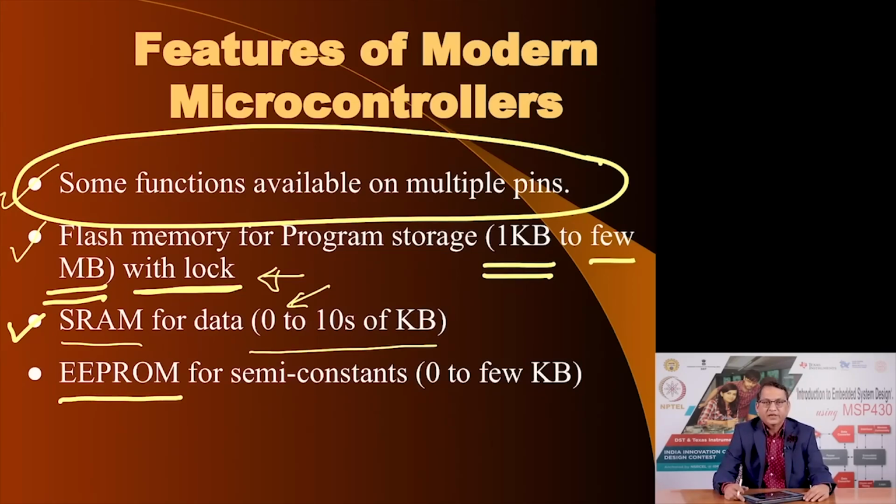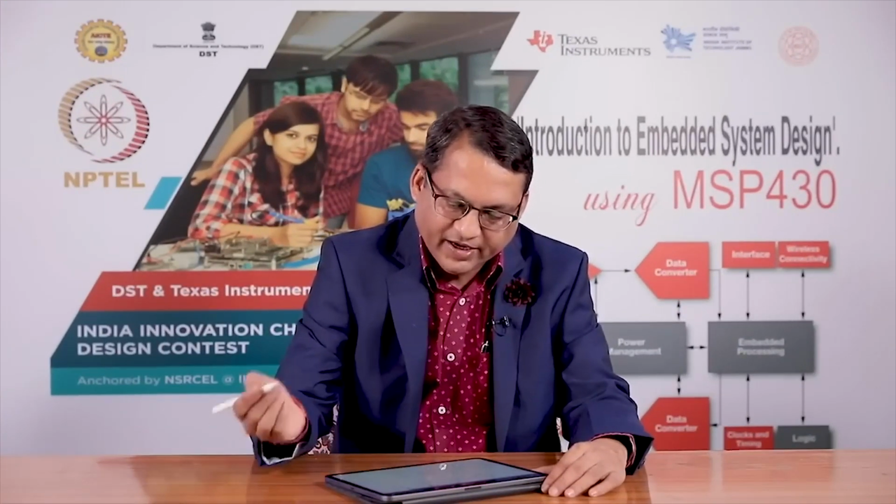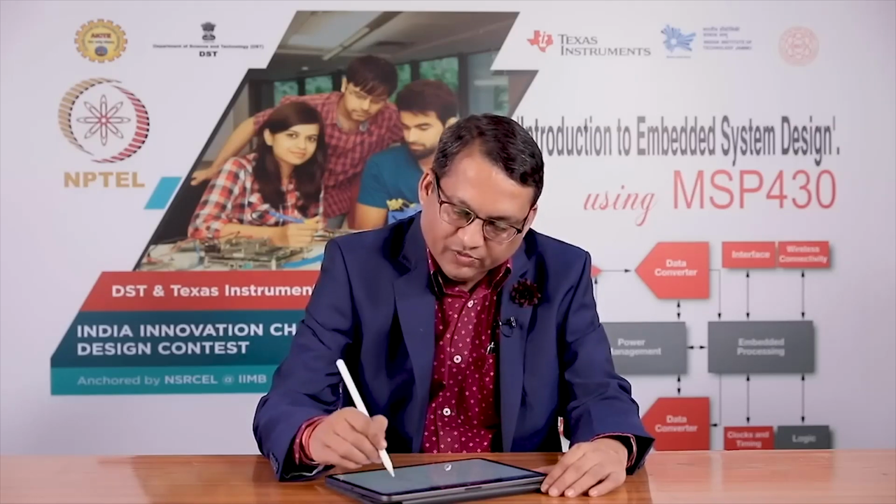EEPROM stands for electrically erasable programmable read-only memory, and I use a term which I have coined, I call it semi-constants, and the amount of EEPROM available could be anywhere from 0 kilobytes, which means no EEPROM, to a few kilobytes. What is semi-constant? You may not have normally heard this term. I have specifically created it to indicate a constant, a value which is constant most of the time, but once in a while you may want to change it, right.